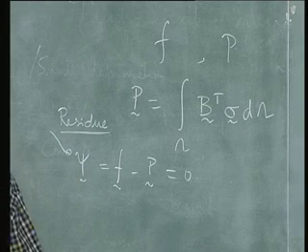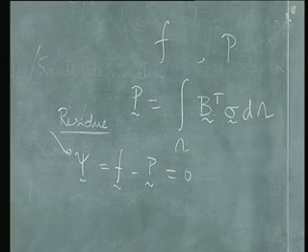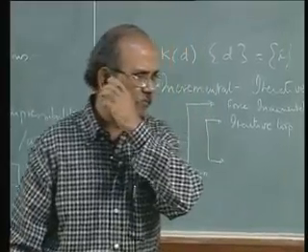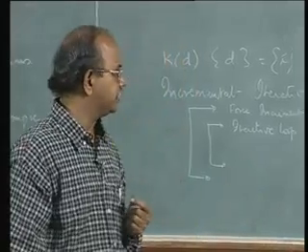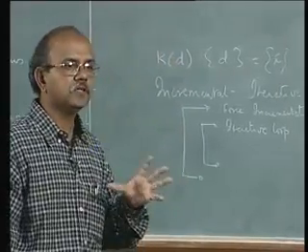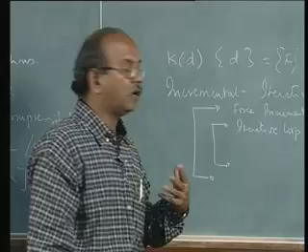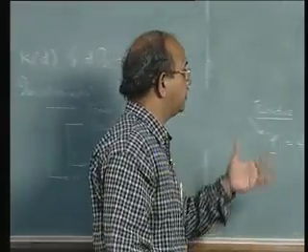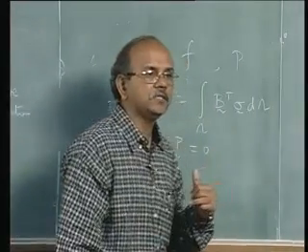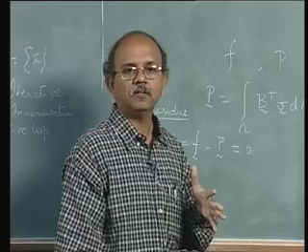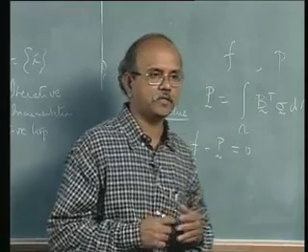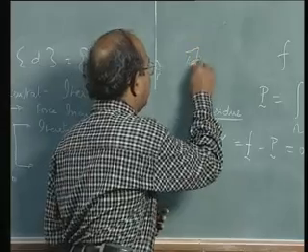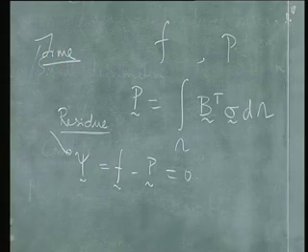Right. Now, before we go further, a small introduction to terminology, because especially when you use finite element software packages, they may not use just increment of load, but they would talk in terms of time. Most of the software talks in terms of time, application of incremental loads in terms of time.